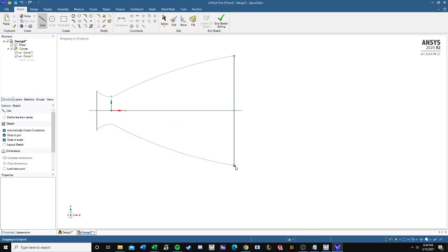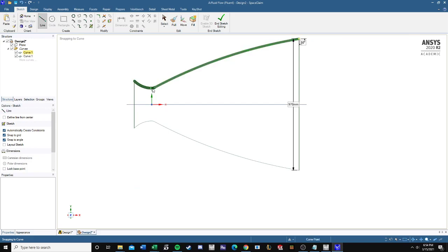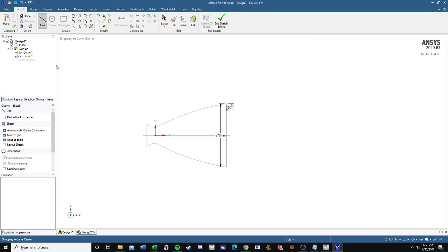For the conical nozzle, all I did was come over here to where I'm about to dimension now and find the lowest point, which was the correct throat radius that we had, and then just delete all the rest of the line to the other side by using the trim tool. It's right there. Yeah, I just made a line from the y-axis, so it always lined up with the correct throat radius.